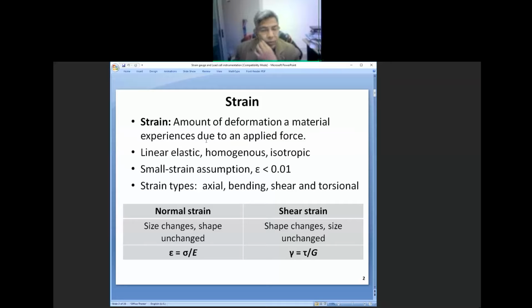And so let's move. Then something next comes. That's called your linear elastic behavior. Because in all our courses on solid mechanics, we learned something called Hooke's law, and that Hooke's law is based on certain assumptions. What are those assumptions? That our material is elastic, and especially it is linear elastic. What do you mean by linear elastic? Linear elastic means my material's stress strain diagram is linearly proportional to each other.